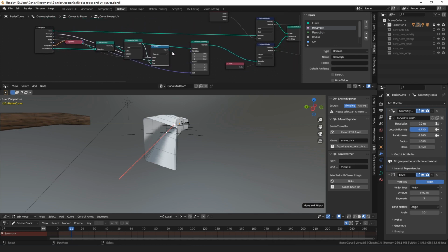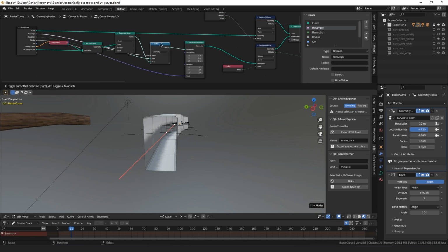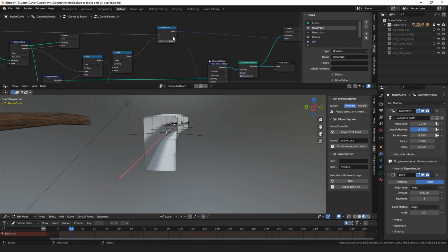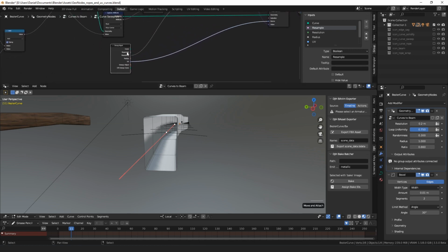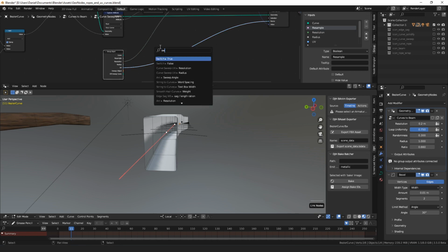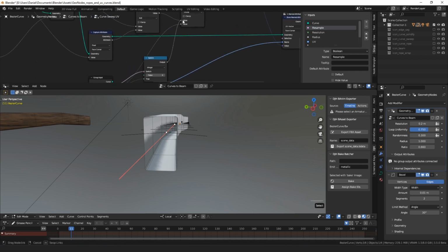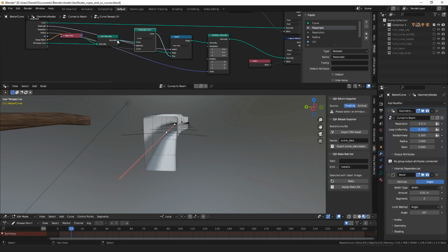Then if we skip the resample node, we need to know the count, for UV purposes. So over here where we set the UVs, we divide by the resolution. So we need to do a switch here on the resolution. If resample is true, that's fine. Otherwise we need our curve that we start with.